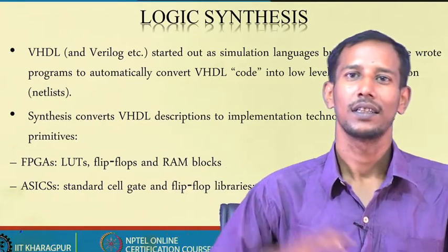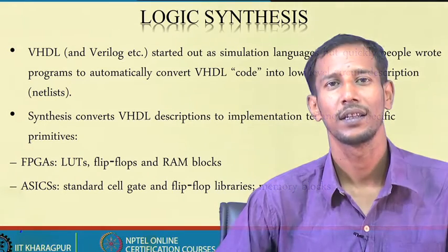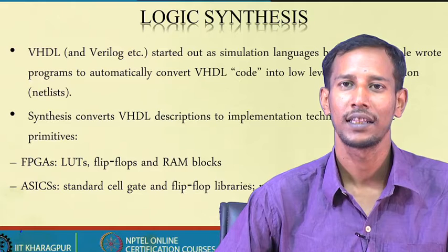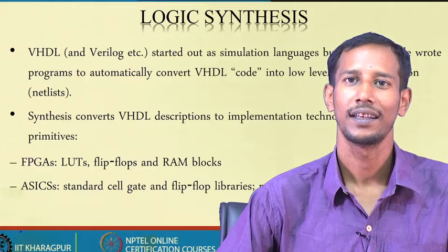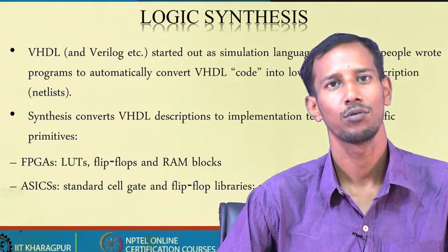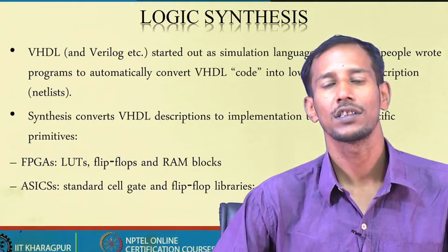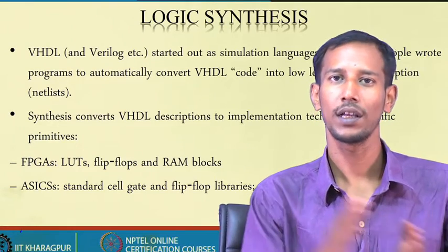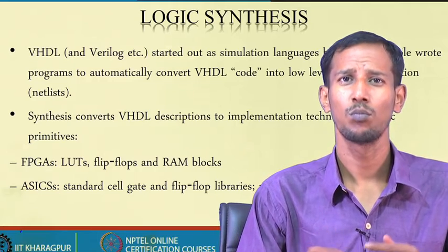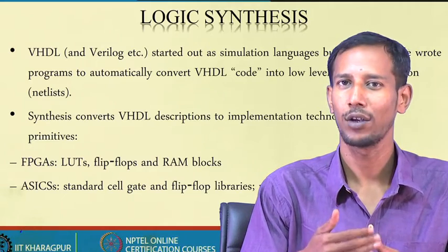So, yesterday we have seen that the FPGA design style has to start with specification, then the RTL specification or detail design, then function simulation, then synthesis, then timing simulation, and then you can go for the device programming part. And what I said is that logic synthesis is the part for converting from the logical expression to the gate level netlist. Okay. So, let me add a bit more on what logic synthesis means.